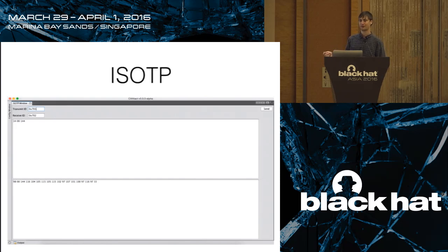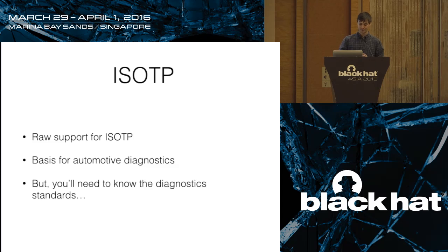What this is also useful for is that some manufacturers implement their own non-unified diagnostic services, services that you won't find in any standard anywhere. So you might need to be able to talk in individual bytes. So it supports this raw ISOTP format. It is the basis for automotive diagnostics, so it provides the ability to do these longer frames. But you need to know the standards in order to actually do anything.